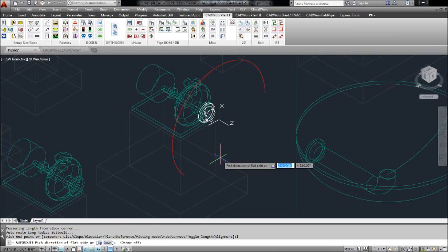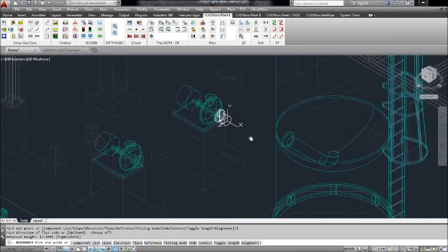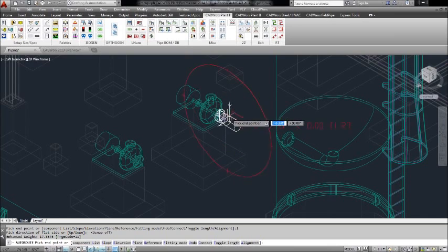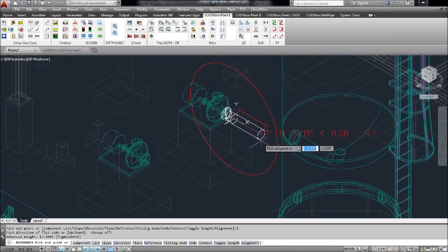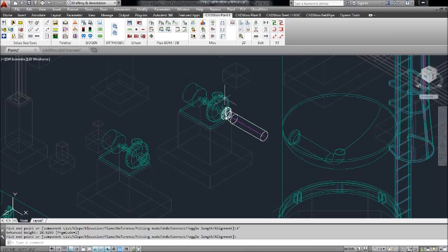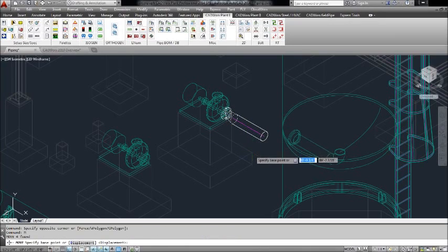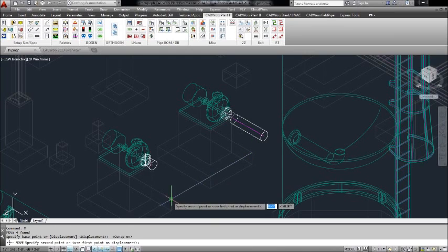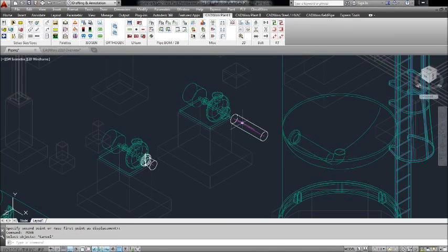It's important to pay attention to the actual direction that you're getting. So I'm going to pull down and click, and now I'm routing again, and you see CADWorx gave me that connection criteria there. It gave me my gasket, bolt, and flange. That's all just part of the automation that you can take advantage of here. Now I'm going to put in a 3-foot spool piece here, and then I'm going to cancel the router and just take this as an opportunity to use some AutoCAD to replicate what I've already done once so I don't have to do it again.